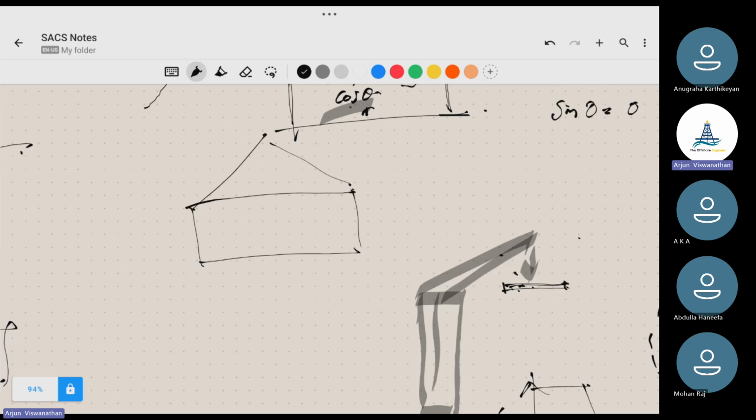So we need to arrest this rigid body movement. As a general case, it is a common industrial practice, though I have never seen it written anywhere, to provide weak springs at the bottommost corners.